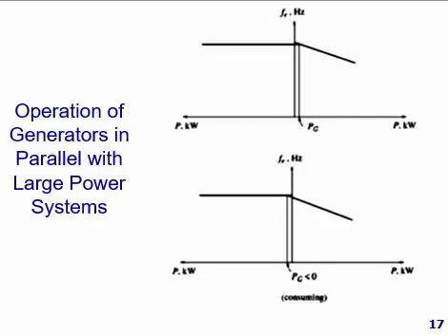So to ensure that the generator comes online supplying power instead of consuming it, the oncoming machine's frequency is adjusted slightly higher than the running system frequency. As we said, it is ideal that the frequency of the new oncoming machine should be slightly higher than the running system frequency.